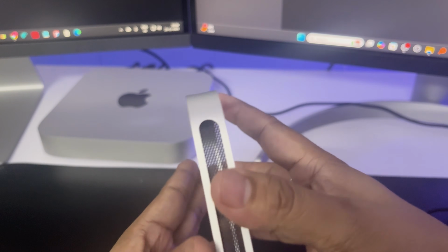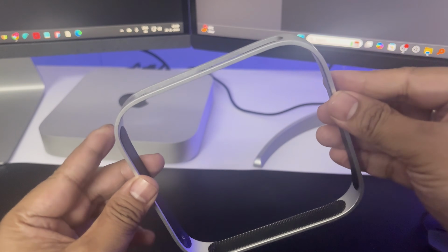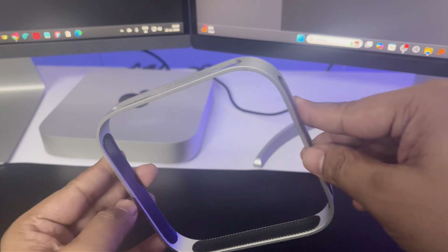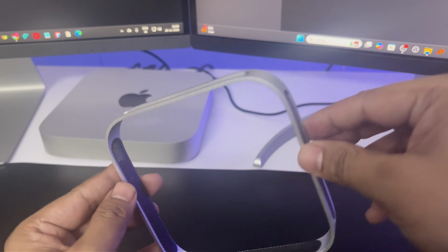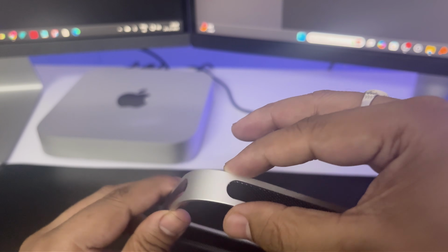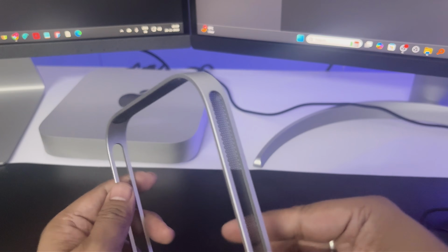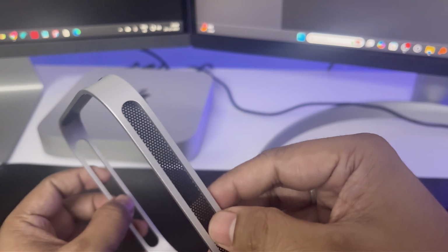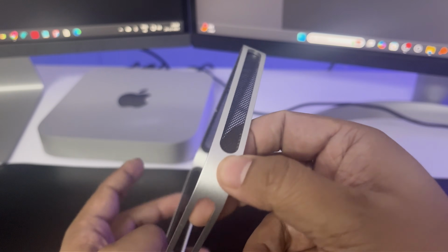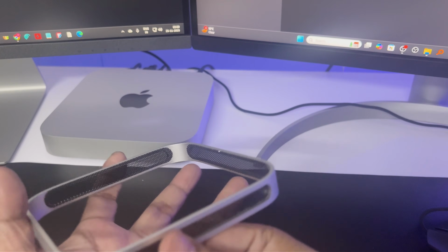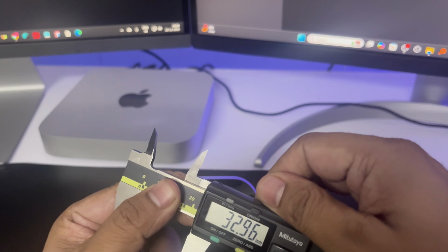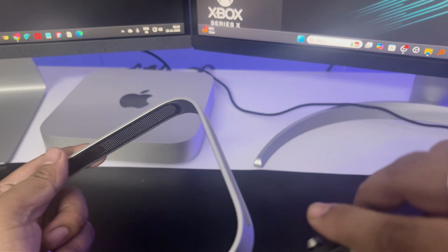Sometimes the value may change based on the way you are measuring, so it is very important to measure the parts in a correct way, especially if the parts are precise metal components. Now we have the width of it, which is 15 mm. Now let's talk about the next step, which is understanding these slots. It seems like all four slots are almost the same, which can be verified using the external jaw of the vernier caliper. I am going to make it a little bit loose also, and see how much it is.